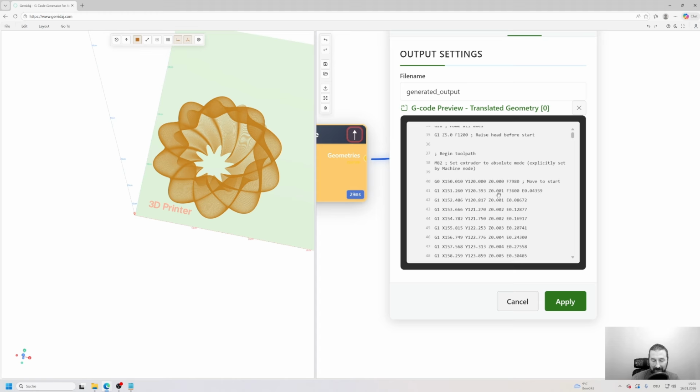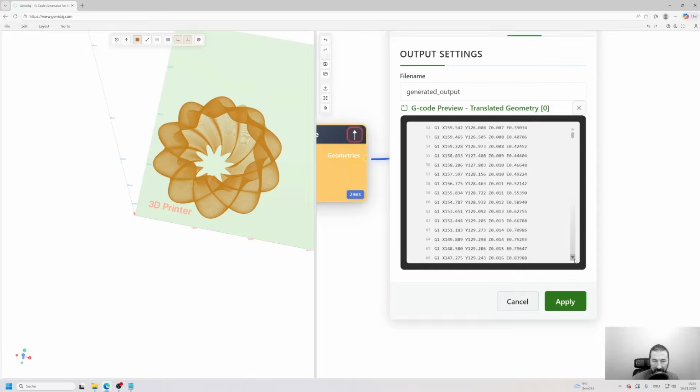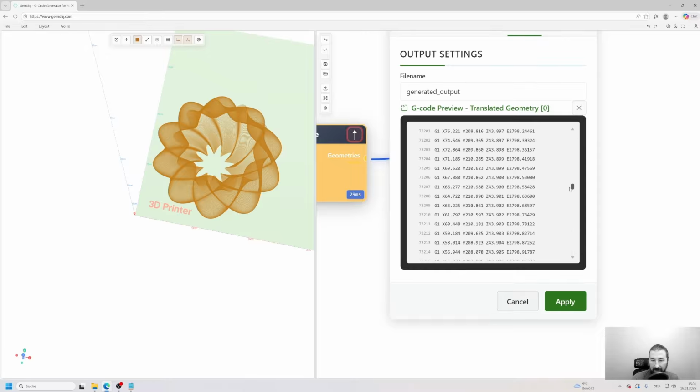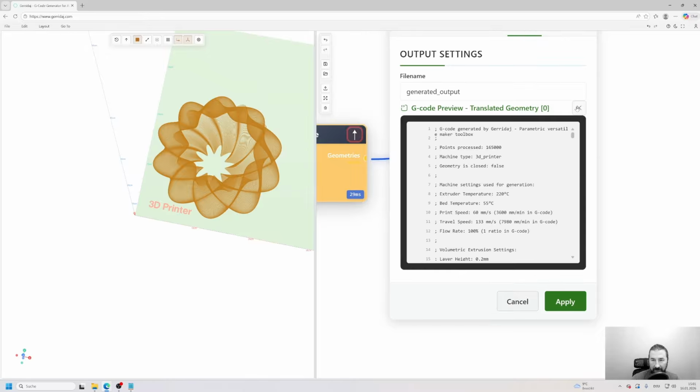And what I explained to you about this continuous Z change, this is what you see here. The Z command is not like a normal slicer. Okay, in the vase mode, a normal slicer does that as well. But in normal layer by layer slicing, you have Z jumps which are much larger than that, and they are not that frequent. And here, at any point or any second point, you have a different Z height. So this creates a print path which has no seams. And that's it. That's your G-code. You can download it and print it.